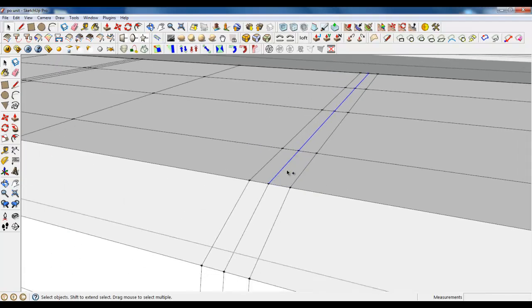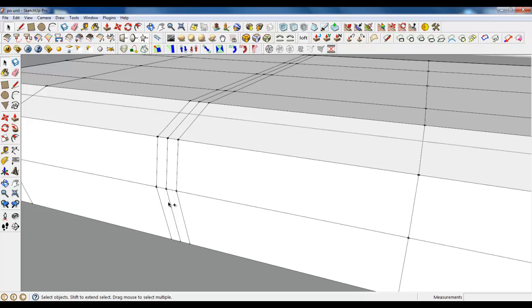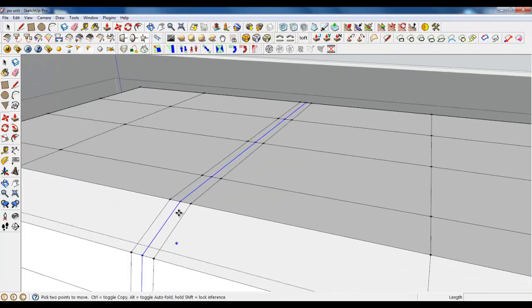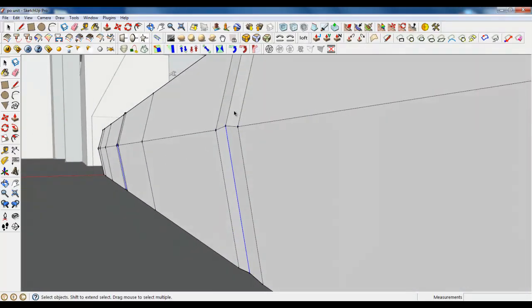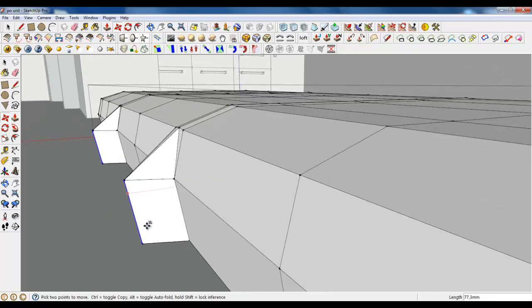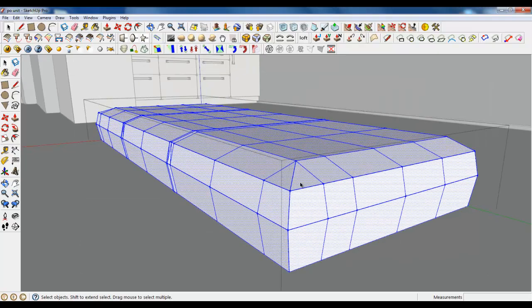But let's create some bump, as I said, and these middle ones. Drag them in this position, 2 millimeters. Select these 2 lines because we are not out but in, and make them out. Use your arrow keys. It's 3 millimeters. Now select everything and use subdivide tool.